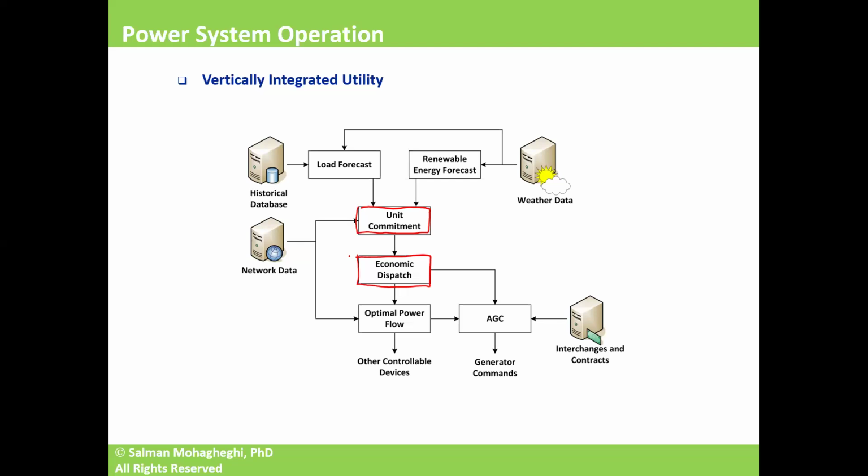Economic dispatch is typically run every, let's say, 30 minutes to an hour. But even between these solutions, between every 1 hour window, a 30-minute window, demand and renewable energy resources still change. So we're going to have to, again, go ahead and update the amount of power exchange between these resources and the grid. This is the job of optimal power flow.